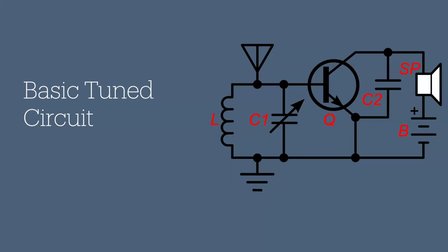Because that oscillation is occurring across the capacitor, it is made available to the rest of the circuitry. The rest of the circuitry then splits off the high-speed alternating current using the transistor. That Q object there is a transistor. That's one transistor. That's all it is. The output voltage then is the high-frequency component of that signal, which is bled down to Earth, and the low-frequency component, which is probably a voice or something being turned on and off, gets through to the terminal just near the speaker, and you hear the sound. That's really all there is to it. But the real key to it is that resonance circuit, the L and the C1. So that's the basics of it.